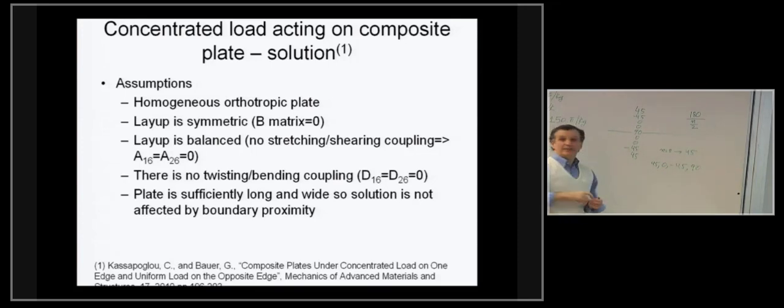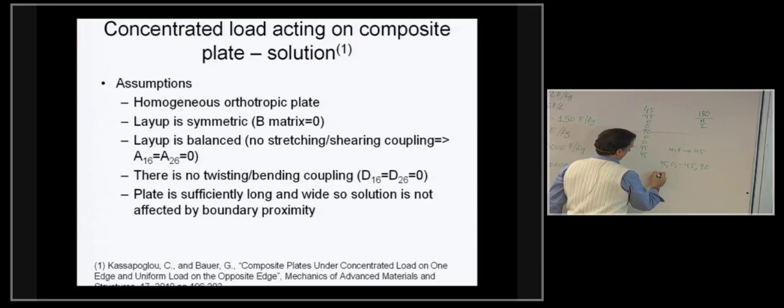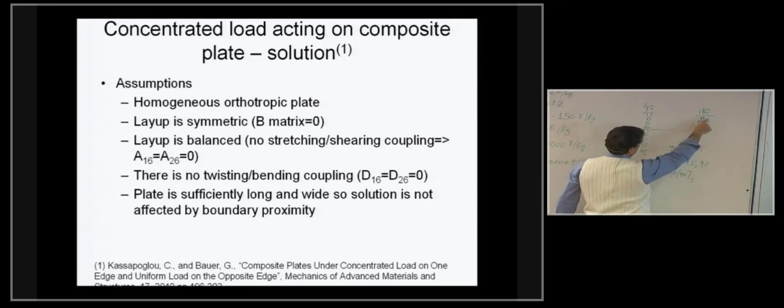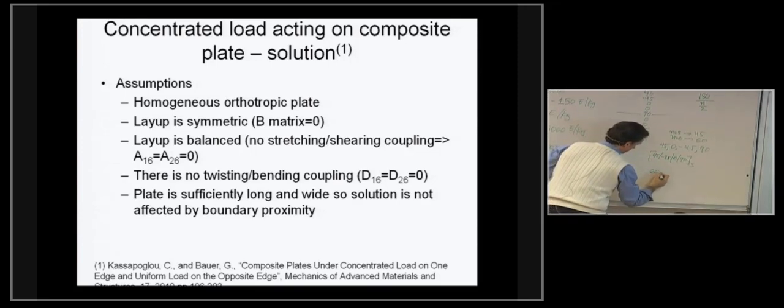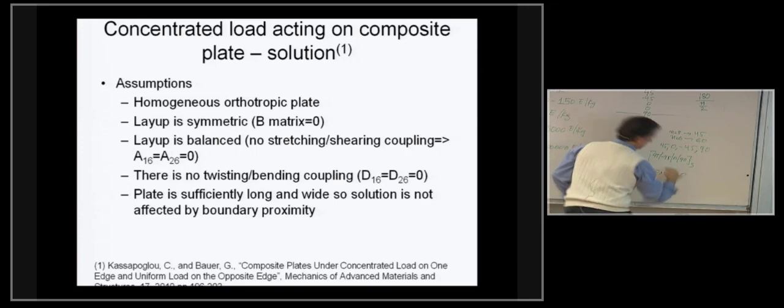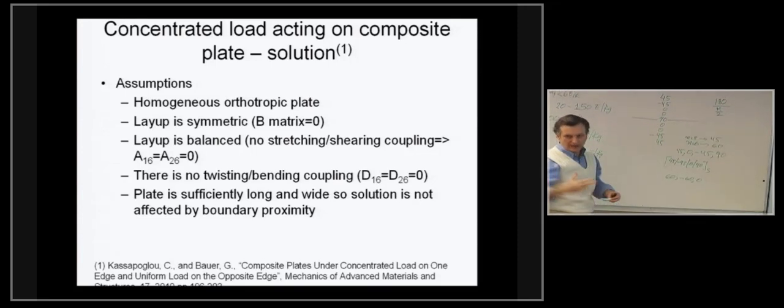So a symmetric laminate that uses these in any combination or any order would be quasi-isotropic. So 45, minus 45, 0, 90, symmetric is quasi-isotropic, but so is any permutation of these angles, 45, 0, minus 45, 90, and so on. If instead of n being 8, I had n equals 6, 6 divided by 2 is 3, 180 divided by 3 is 60. So any combination of 60, minus 60, 0 in a symmetric laminate configuration would give me a quasi-isotropic laminate. And you can change n to anything you want. It's just that after a while you will be getting fractional angles and so on.